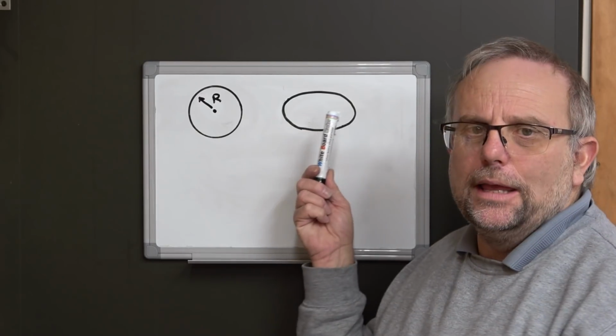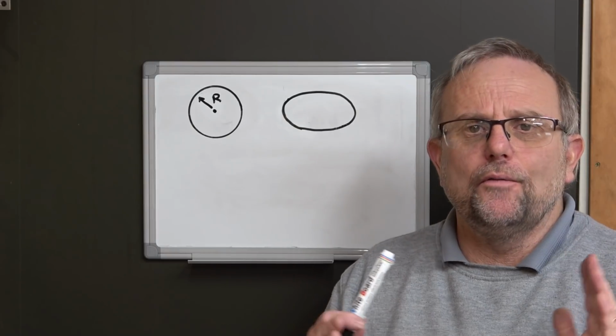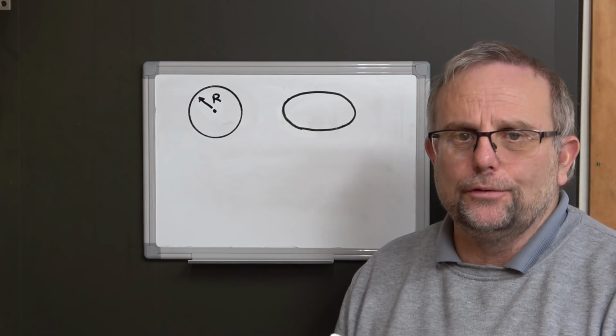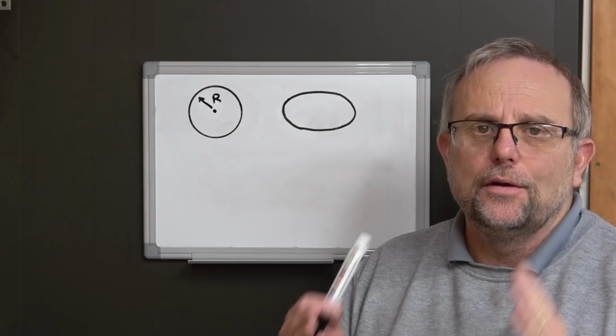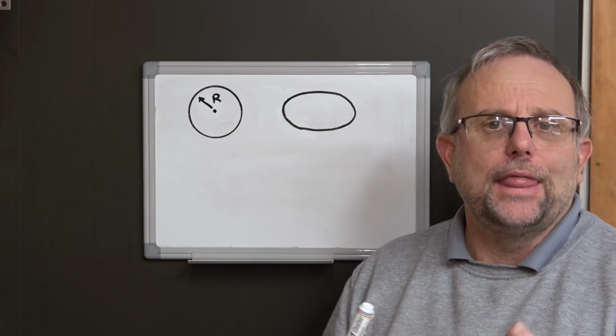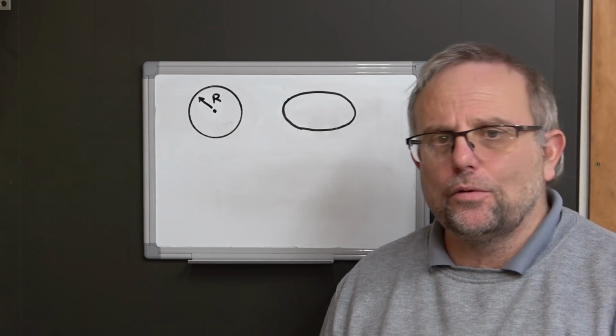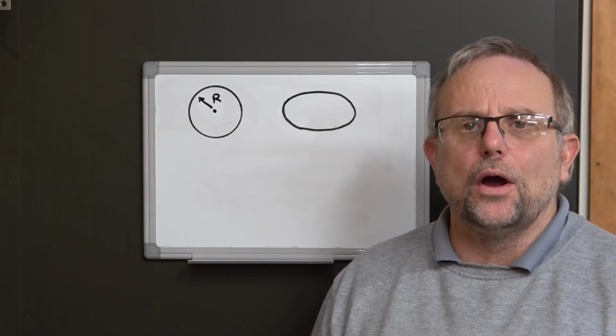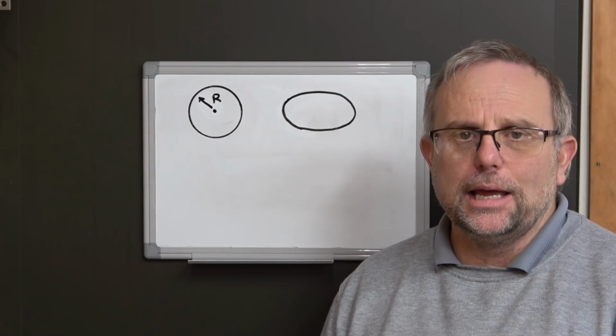So this oval here is made up of what are known as Bezier curves. We could see them in our CAD software, 4 distinct nodes, and they were Bezier curves. They cannot be described in G-code because G-code only describes circular arcs.